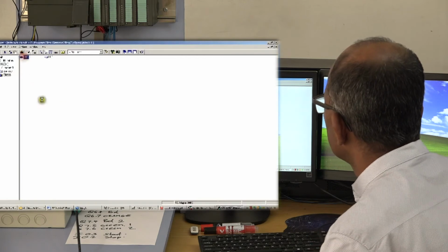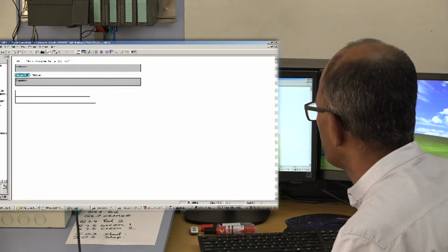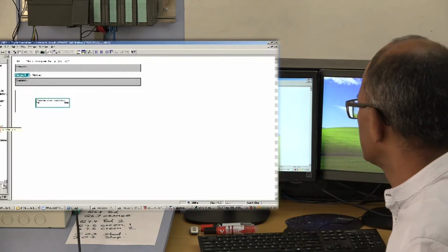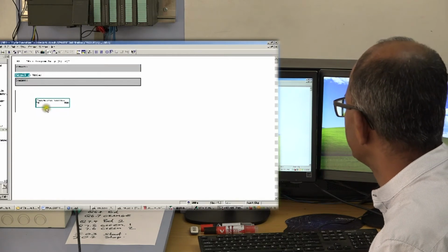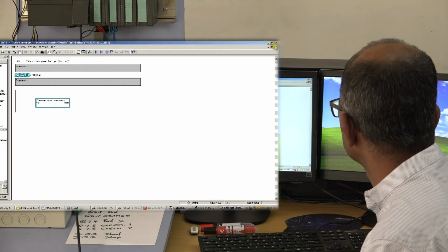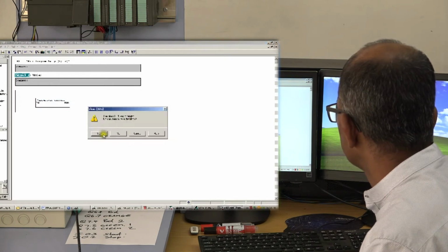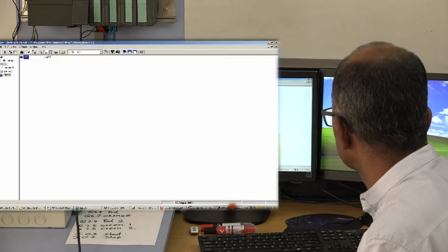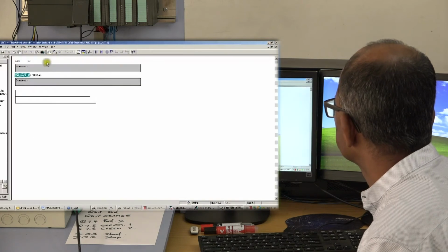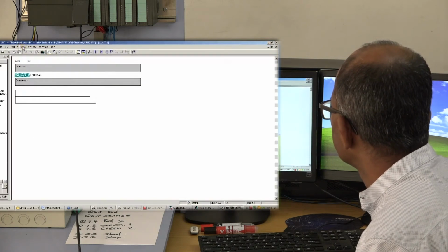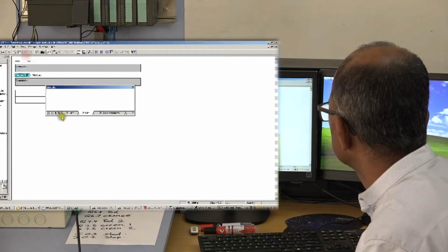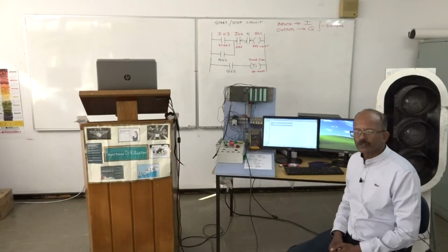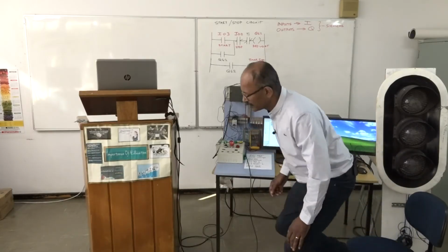Okay, remember I said we also have to tell my operating block which one to use. So I'm only going to use FC1, which is my interlocking circuit. And you can see here, OB1 will only be using my interlocking circuit. Let's change, yes, save changes. I'm going to close this. Okay, FC1, view details. Okay, FC1 is now blank, and I have to program my interlocking circuit in it.